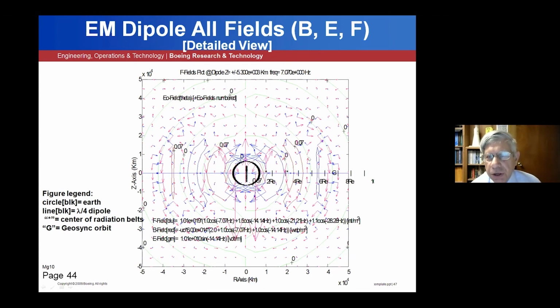And then you got your alternating shells. Now, all these pictures show only 1/2 cycle of the AC. When the B field will reverse from up to down, and the E field will spin the opposite direction, but the force vectors do not change direction because of the cross product. They just pulse in and out from 0 to maximum and back and forth.